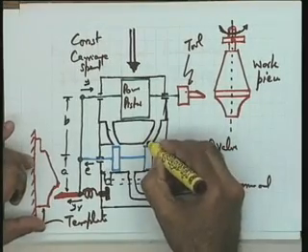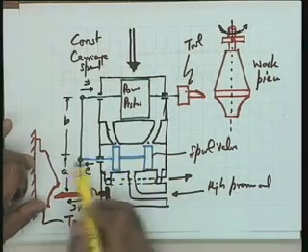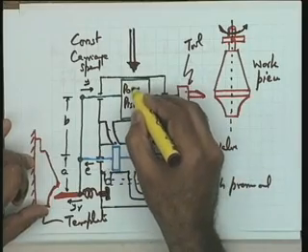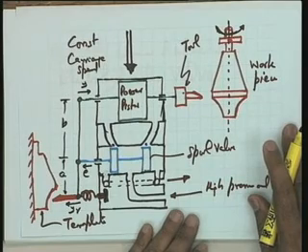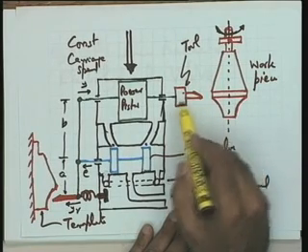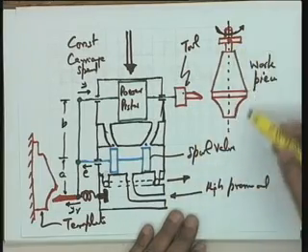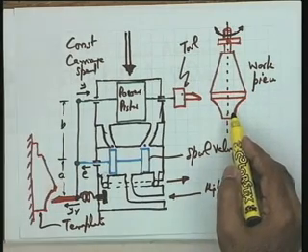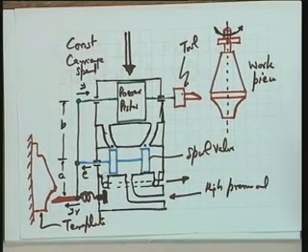These two are obviously the control ports. So, the oil to the control ports is going to be suitably controlled by the movement of the spool, which is going to control the power piston motion and hence the load. The load in this particular case is the load of the tool, the associated friction, and how about the disturbance? The reaction force on the tool is going to provide the disturbance on the system, and the reaction force will depend upon the job to be done, the hardness of the material, and so many other factors. Therefore, the reaction force is uncontrolled and will act as a disturbance on the system.